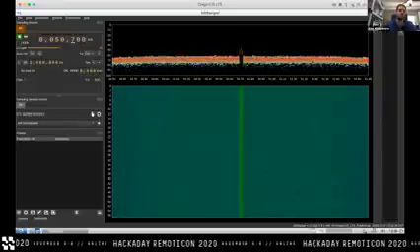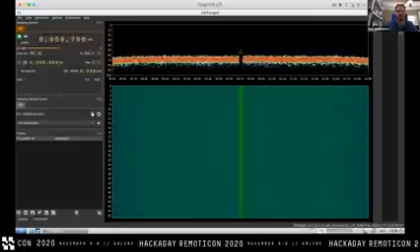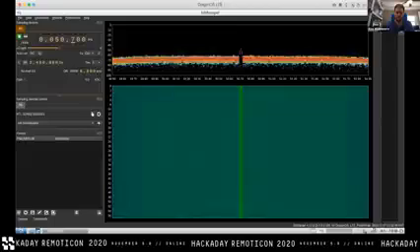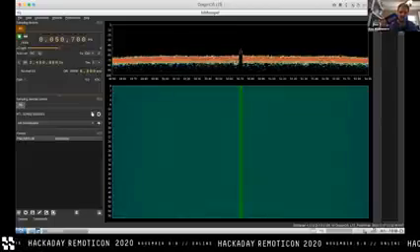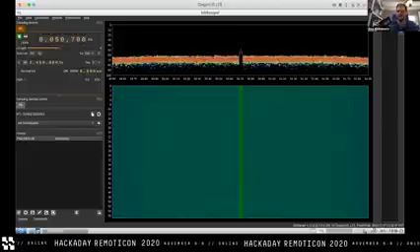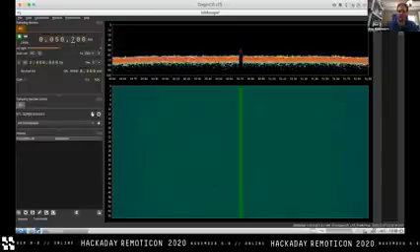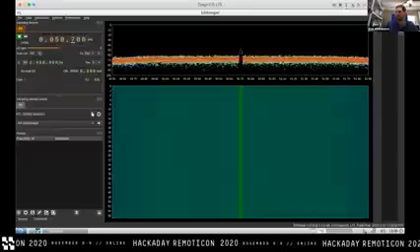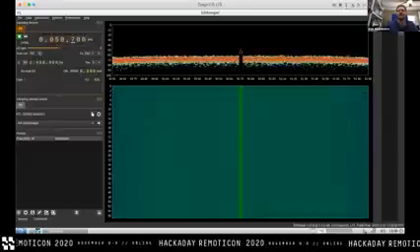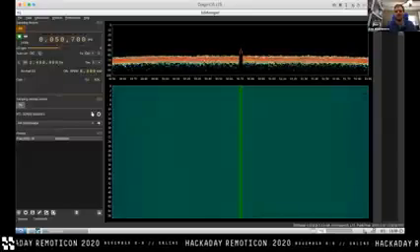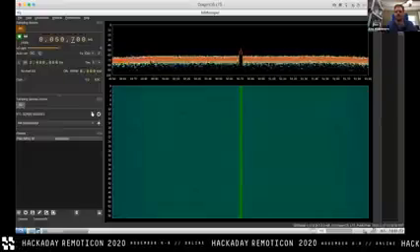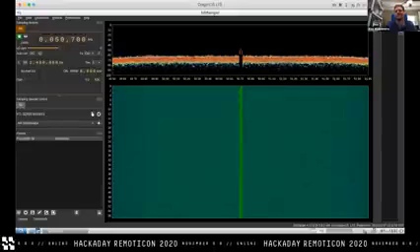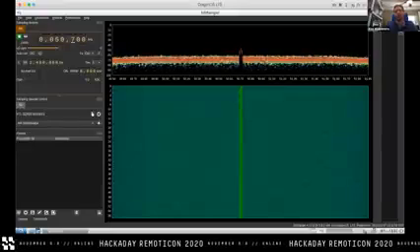So one way is to spend more money on an SDR. This RTL SDR has 2.4 megahertz bandwidth. This HackRF1 has 20 megahertz bandwidth, so nearly a 10x improvement. This Lime SDR has 60 megahertz bandwidth, so a 3 times improvement even over that. And 60 megahertz is dangerously close to that 80 megahertz wide 2.4 gigahertz spectrum. So that's kind of neat.